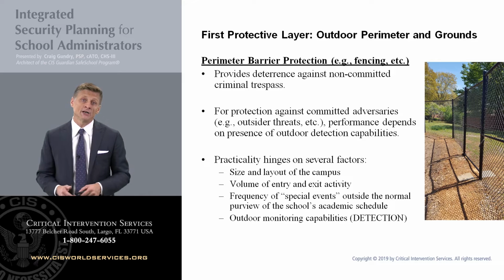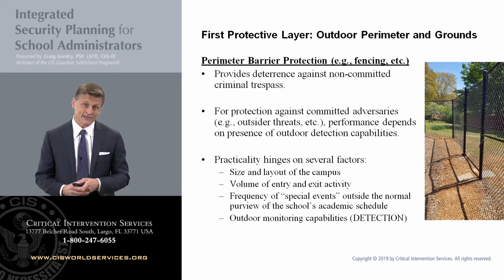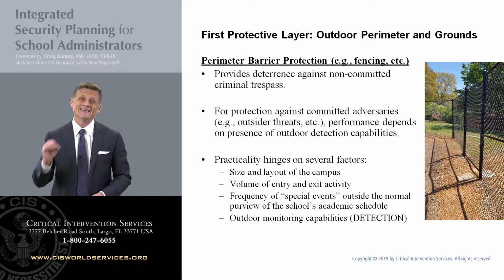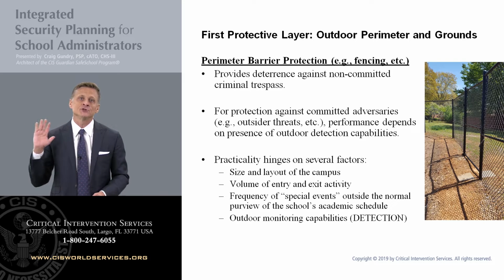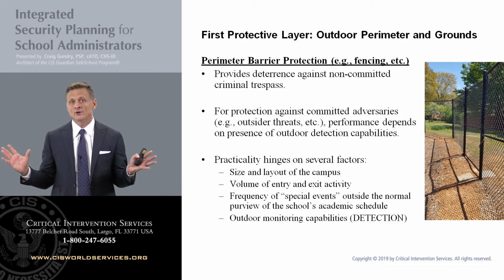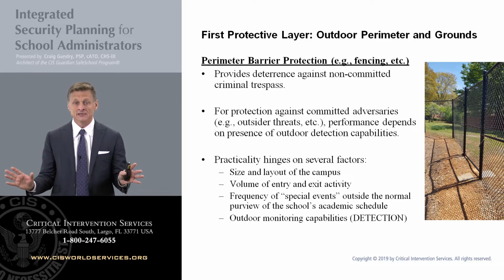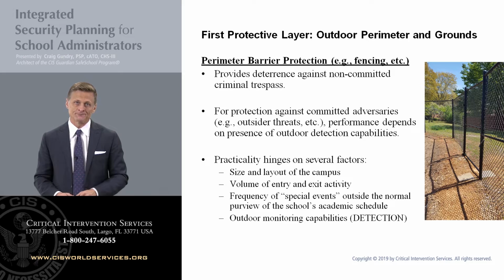Also, I would add to that, outdoor monitoring capabilities. Now, if we were to speak with the experts in physical security design out at Sandia National Laboratories and ask them what the value of a barrier at a perimeter that has no detection elements is, they will tell you 0. It has no value whatsoever in the physical security design. Barrier delay only matters after detection occurs. So if we have a very, very large perimeter and for all purposes, it is not being monitored consistently, then that perimeter fence should not be considered reliable for the purposes of our overall integrated physical security strategy.